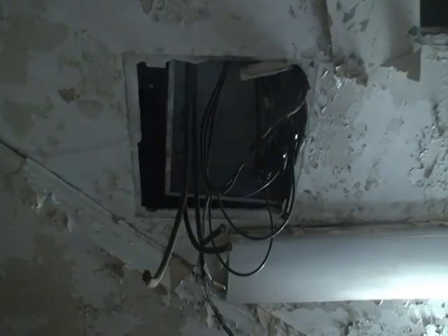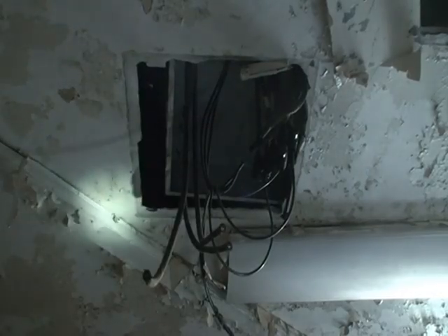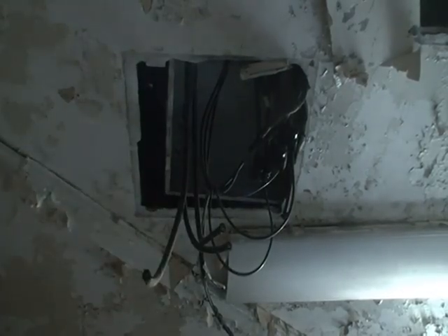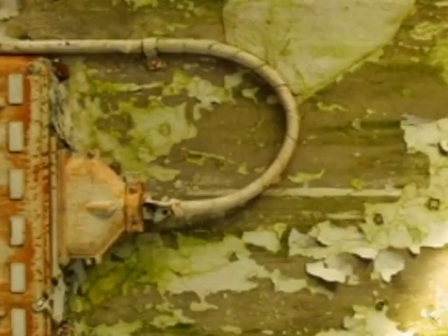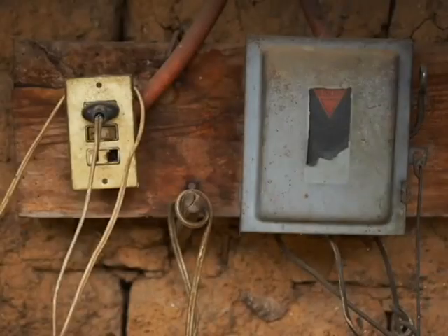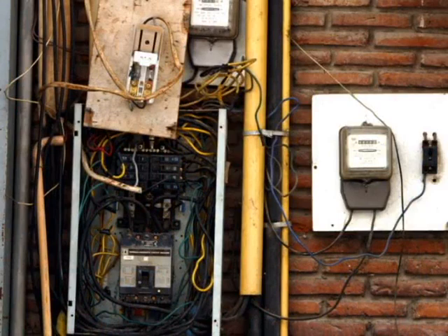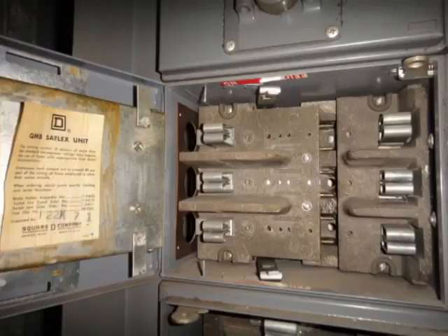Another building material that's frequently overlooked in asbestos inspections performed by contractors is the electrical wiring. The cloth insulation on the outside of old wiring is known to have asbestos in it. If you're doing a follow-up inspection or an oversight inspection in a building, you need to be sure and look at pipe chases and electrical runs to see what kind of wiring you may encounter. You can also find asbestos inside the switch boxes or electrical boxes. Those can contain transformer panels or paper back behind them to prevent fires or help suppress fires.